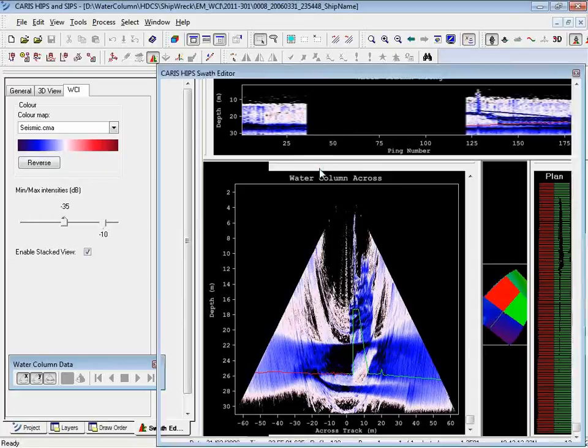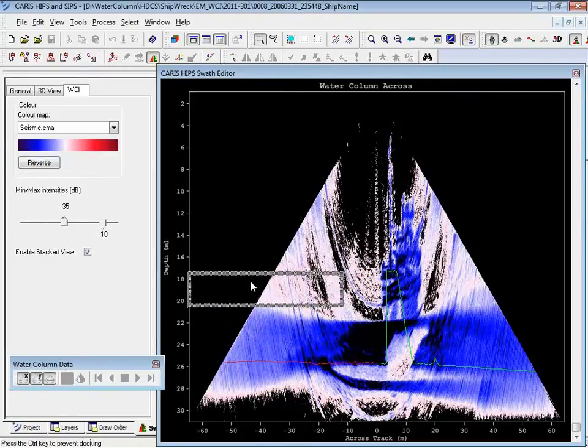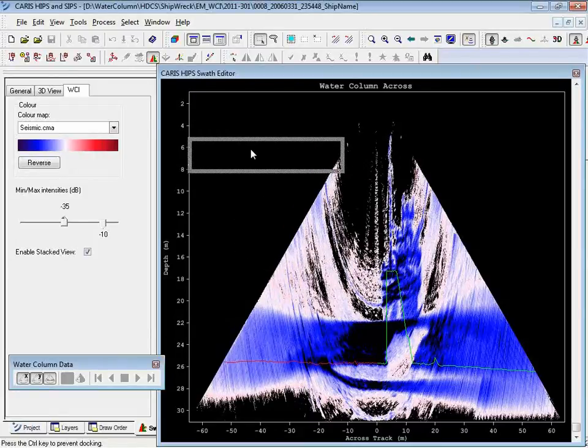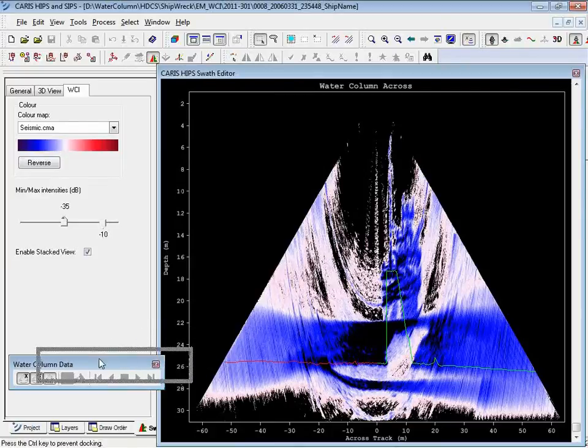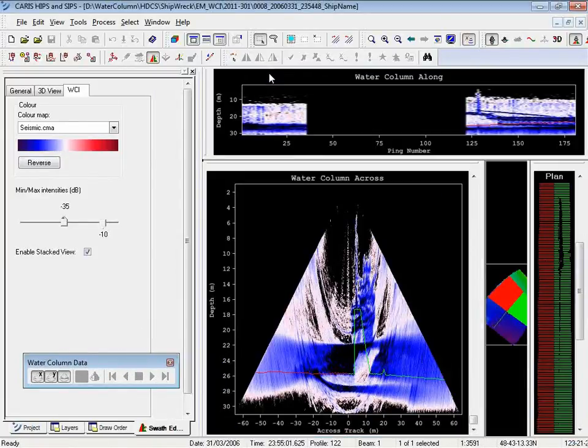The interesting thing about the particular water column image that we're on right now is that you can see right here, this is your bottom detection, but your least depth is way up here. So this is where it can become really handy. We're looking at about 17 meters on your bottom detection. Then we can come up here and we're looking at about 5 meters in your actual water column. So you either need to go back and verify that with more multibeam or a diver or whatever. Very important for chart production to make sure that we're getting that shoal depth in there.